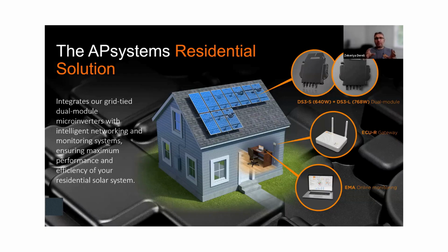Now, keep in mind you don't have a direct communication between the micros and your device, your app or the portal. You need to go through the ECU-R. So it is necessary for you to have this ECU-R for the commissioning and for monitoring purposes.